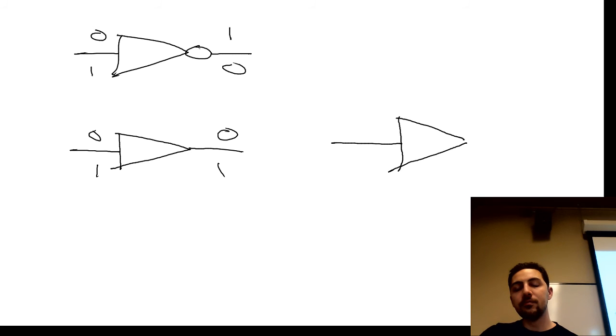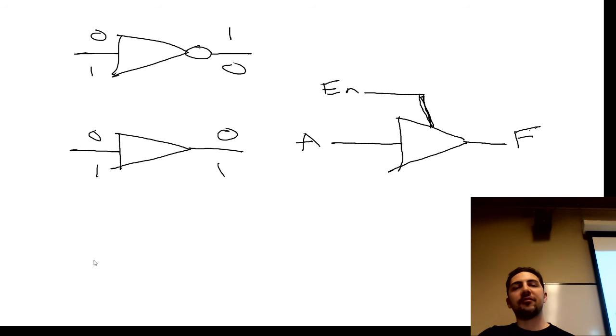And we say that we practice Boolean algebra. Boolean because there are only 2 possible values. Just for this once, we're going to talk about one other possible type of output. I'm going to draw that buffer again. It's a buffer. But off the top of this, I'm going to get one extra control signal. I'm going to call this enable. I'm going to call that A. I'm going to call that F.